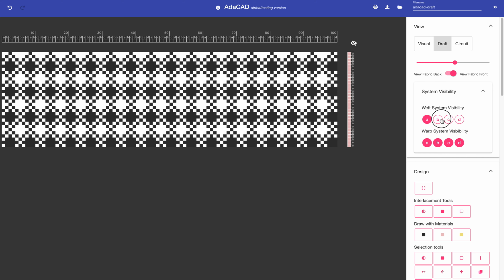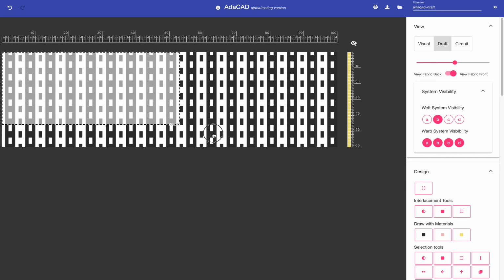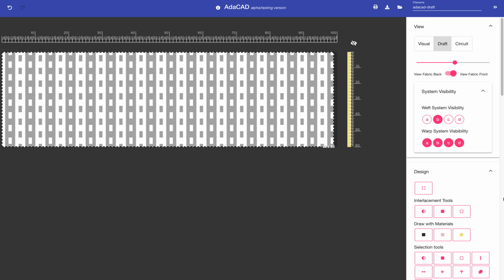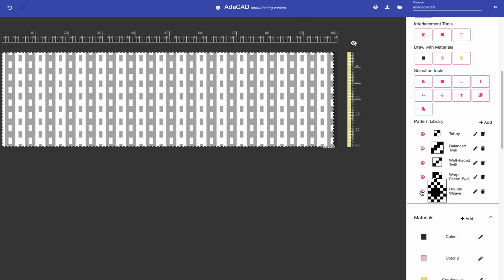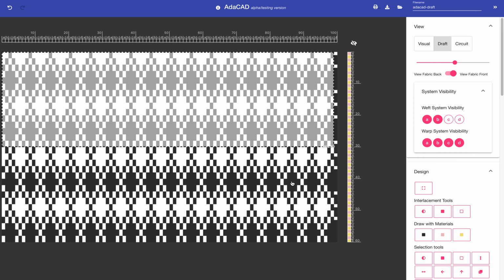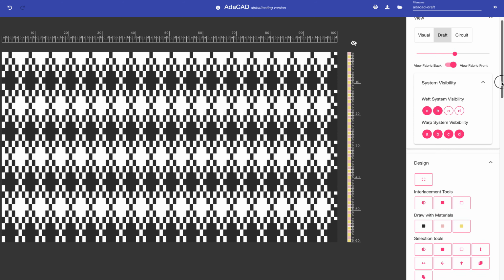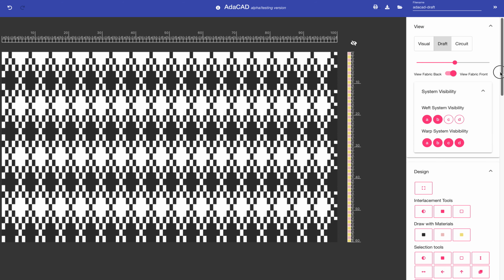Then I'm going to do that exact same thing on the other system. I select it all and fill it with this stitch. Now when I look out, I've basically doubled the height. I've made this a two-pick structure instead of a single pick structure. What that allows me is, because usually the conductive yarns are a lot thinner than the other yarns I'm using, to almost consider that second pick as negligible in size.